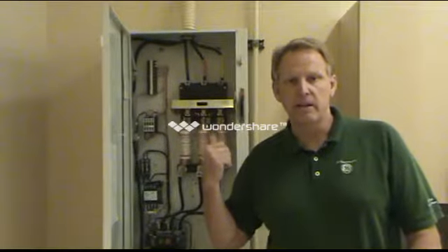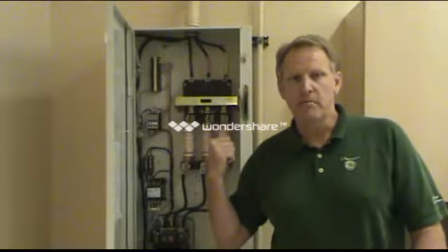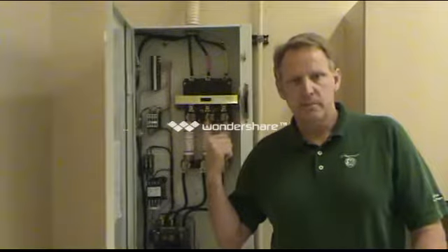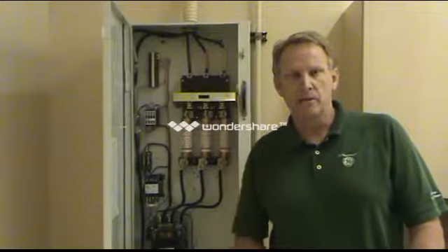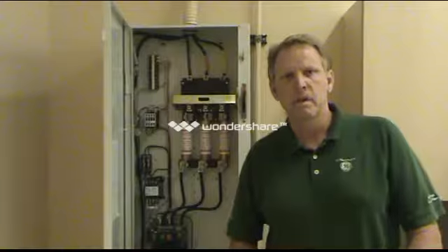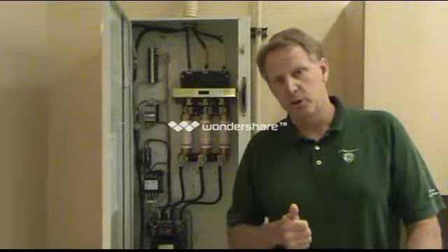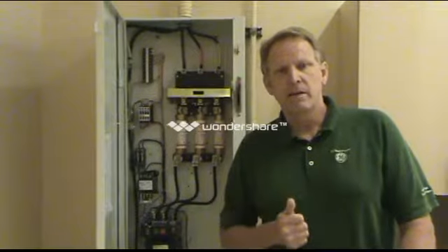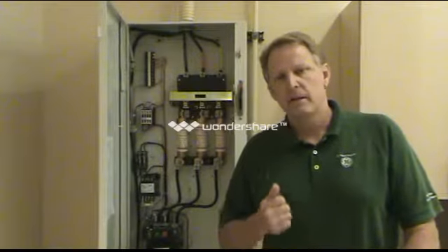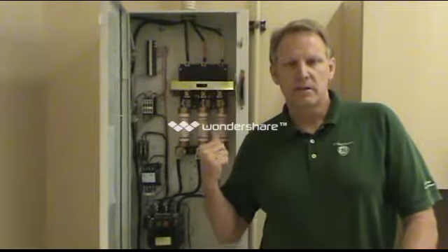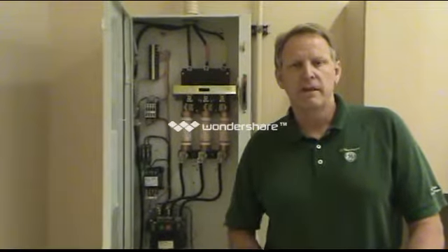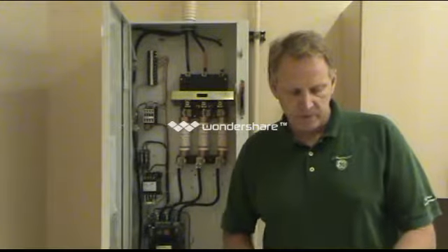This cabinet right here is off. There's no power coming into it. If you guys get into a PDU or an A1 panel, you need to have your arc flash protection on, and a couple of tips. One, if your electrician is around, bring them in to help document the power path. Two, if you have a buddy, bring them in so while you're operating inside the PDU with your arc flash gear, the other person can write down all the measurements while you take the measurements.